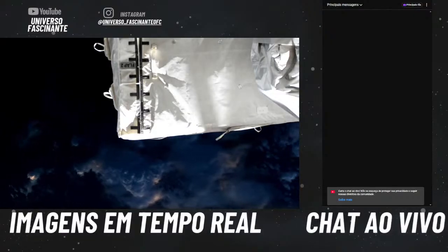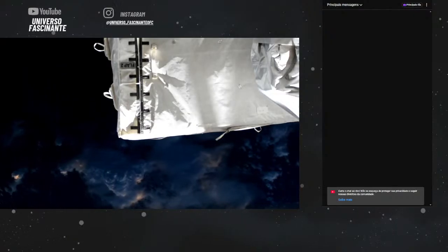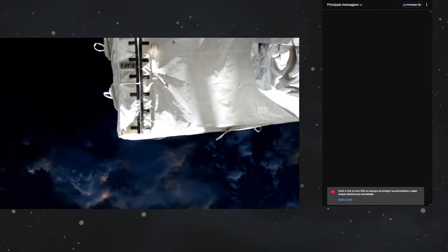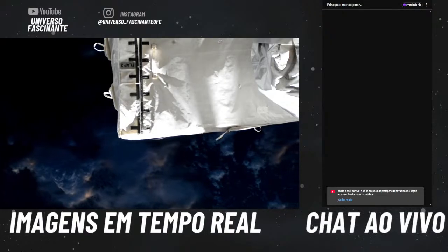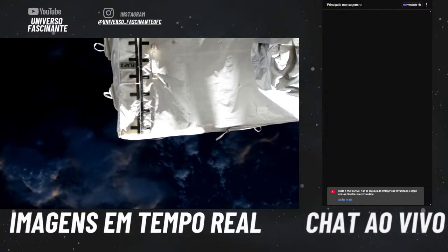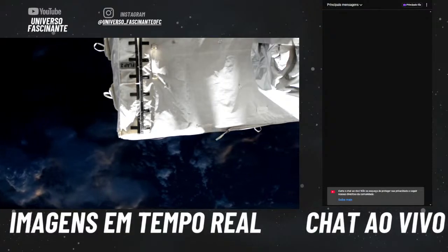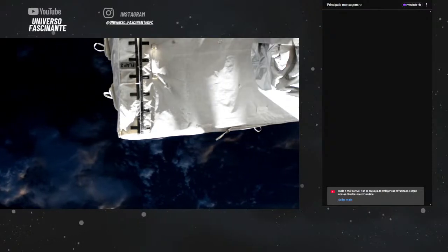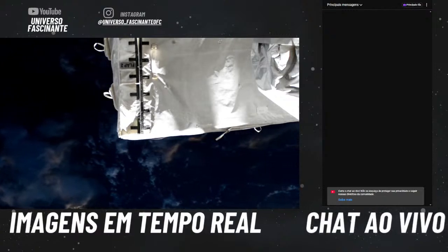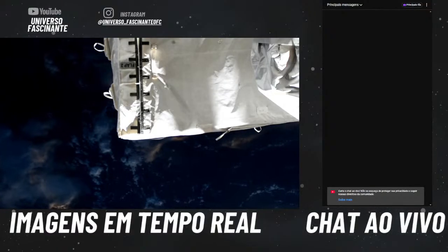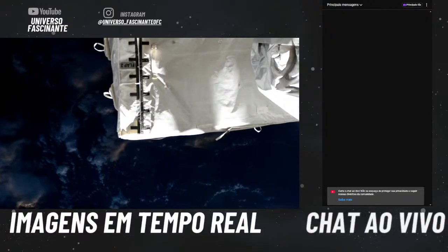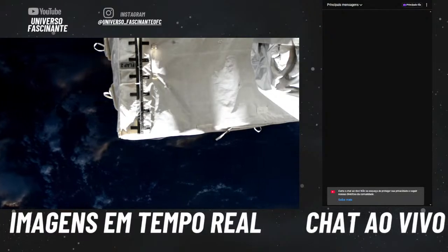The command to open the parachutes on the Soyuz will occur at an altitude of 10.6 kilometers or 6.5 miles above the Earth, 34,777 feet to be precise. That command to open the chutes is expected at 10:49 and 31 seconds p.m. Central Time, 11:49 and 31 seconds p.m. Eastern Time. That parachute deployment sequence is triggered by a barometric pressure sensor at an altitude of 41,000 feet.